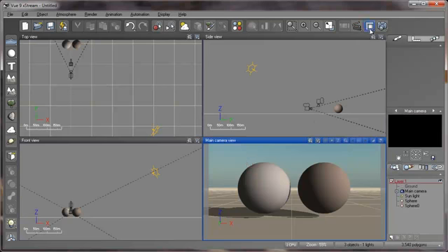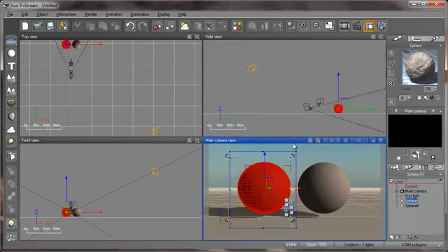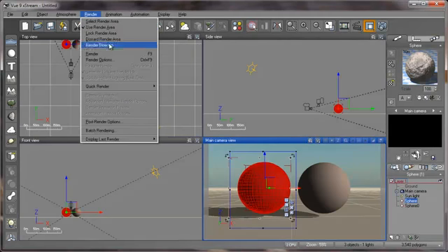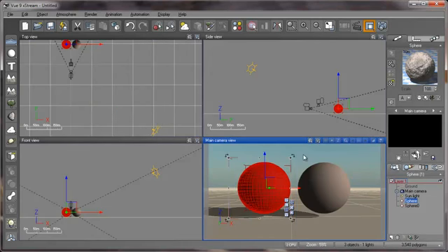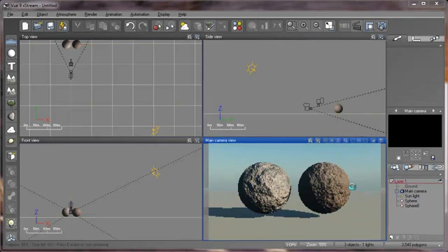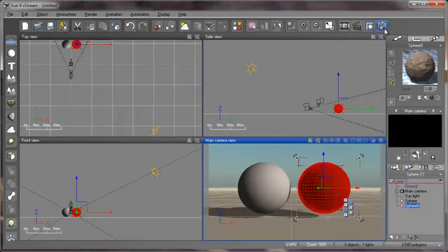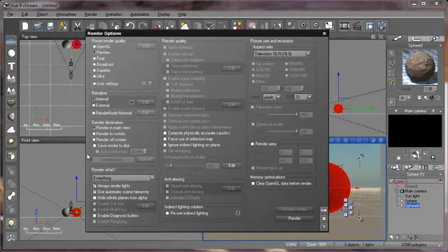And this one is to use region rendering, as you can see. Okay, and we have render here, and to disable rendering here is discard render area. When you click here, you have rendering, escape, and you're okay, stop rendering. And if you right click, we'll have these render options.